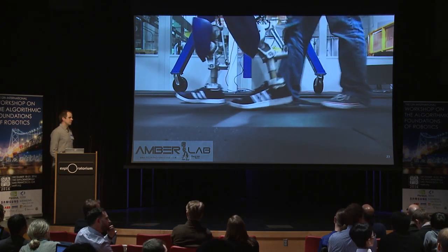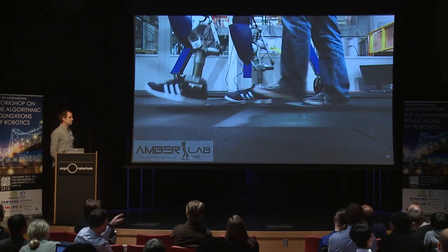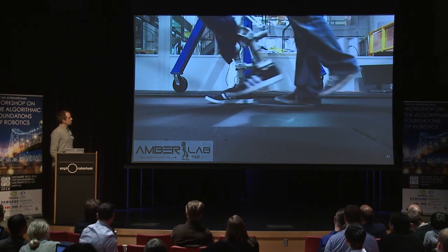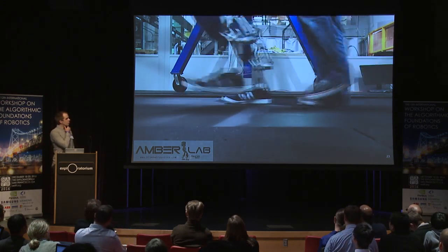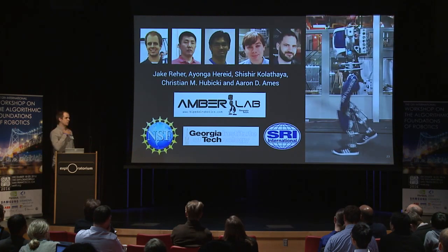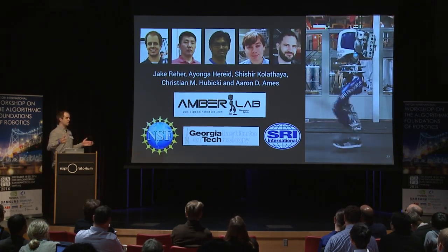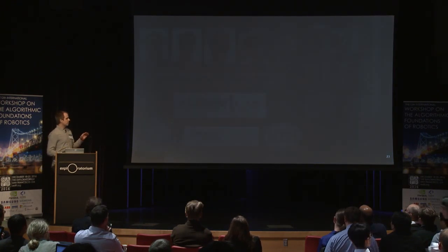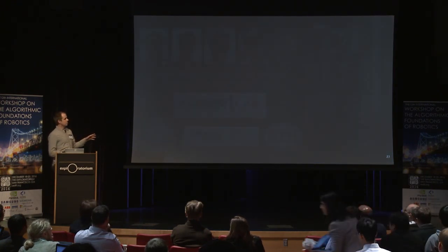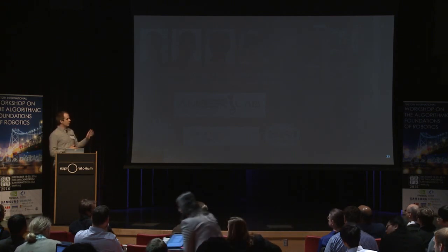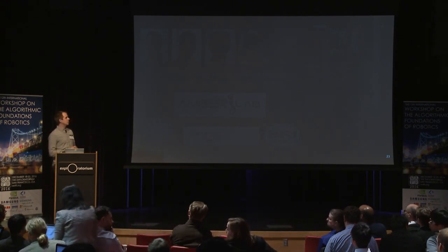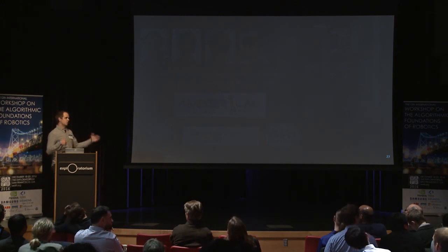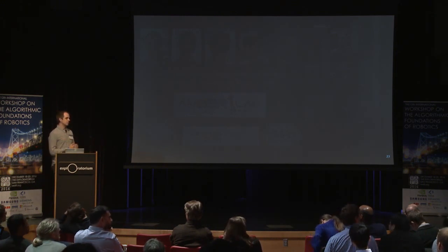So what's the difference between the flat foot and this? Can you explain the energy difference based on the foot? With the flat-footed walking, we're limiting ourselves to the range of motion that we can have with the step length, so we have a much more crouched motion. If the robot has the ability to toe off, even if it's not showing completely in the experiment, that is allowing the optimizer to find gaits that have a much longer step length. That makes sense. Awesome. Thanks.